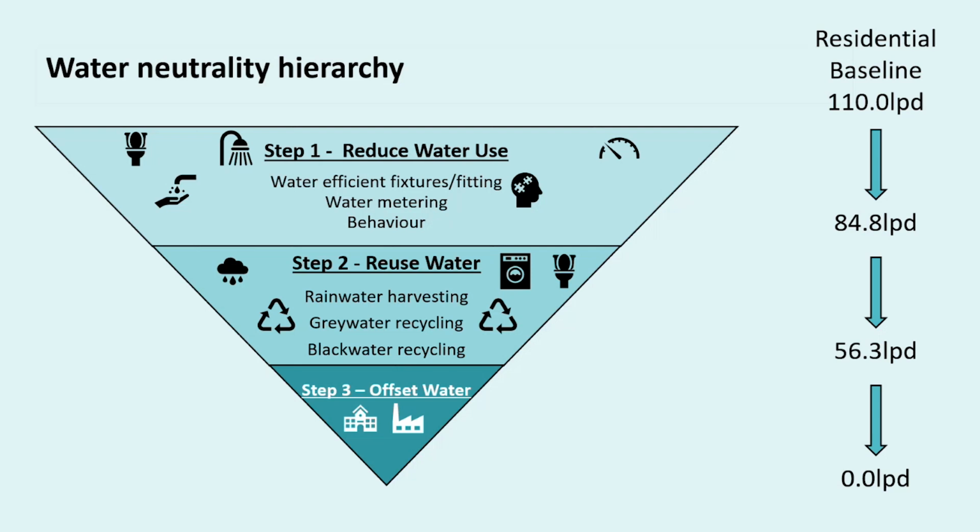Step 3 then could achieve water neutrality through a combination of offsetting water demand from the existing properties on the site, through the yield available from one or more groundwater boreholes, stormwater recycling, retrofitting existing household and commercial properties, or the purchase of credits. And we're likely to envisage pretty much all of those, given the quantum of mitigation required.